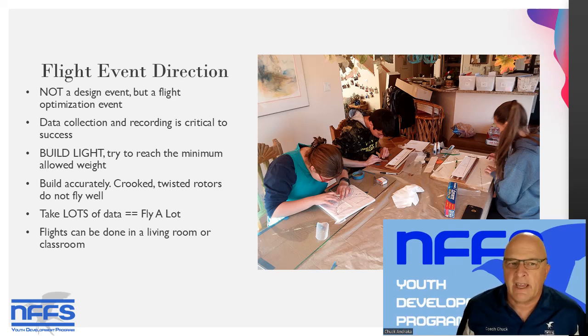Build light. I can't stress this too much. You want to try and reach the minimum allowed weight. Some of the kits will tend to build a little over the minimum weight, and this is because they don't necessarily have the ability to select the best wood for every kit they send out. The helicopters, even more so than the airplanes, depend highly on the weight of the craft, and saving a quarter of a gram could be tens of seconds of flight. So very important to build lightweight. We'll talk about that a little in the building.